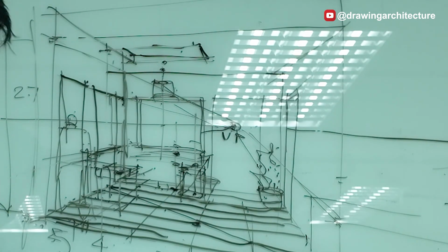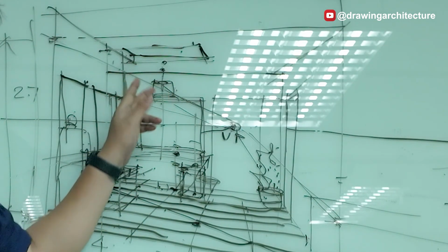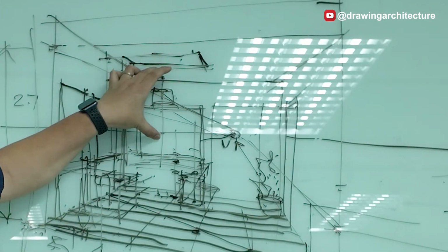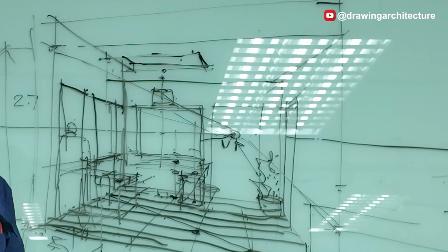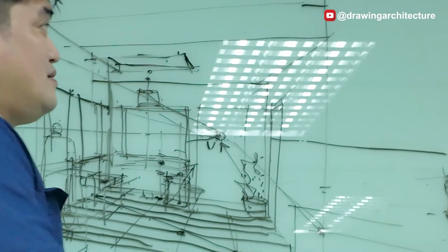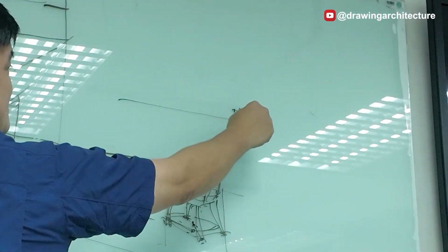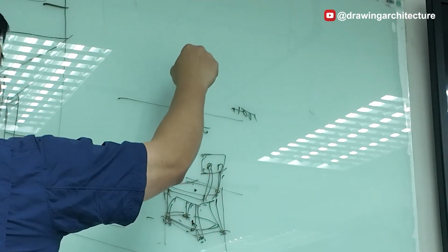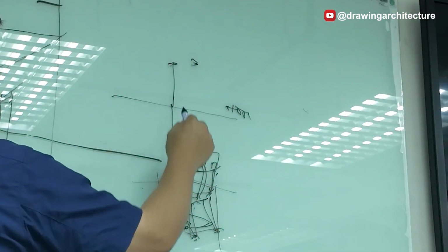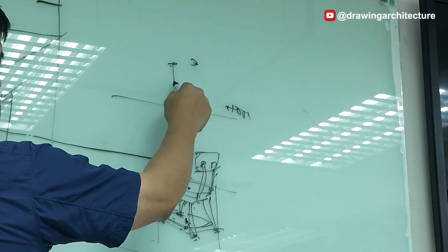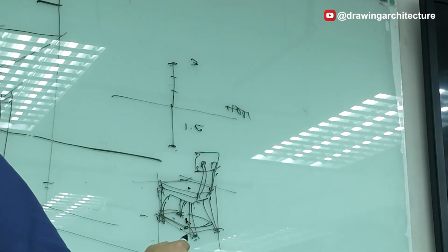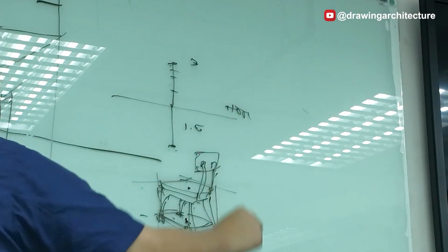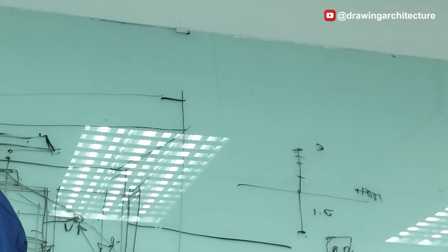Okay? Identify. Relative to the horizon line. And then, equal, then slightly down. Ano yung 2.7 mo? Alam na natin paano if this is the horizon, diba? If this is 1.5 meters, and we put the 3-meter mark there, you subdivide into 3 equal parts. This is 2 meters, this is 2.5, this is 2.75. Are we getting this?